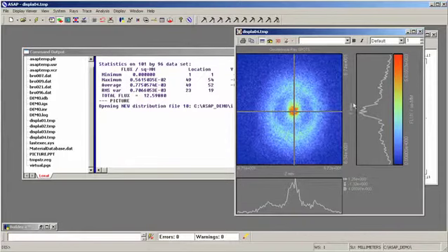So this is the y-axis, here we have the z-axis, and the units here are flux per square millimeter. Depending on how many rays you've specified at the source, you're going to have different levels of statistical noise in the result. If we want to reduce the statistical noise in the result, one thing we can do is go back to the builder window and increase the number of rays.